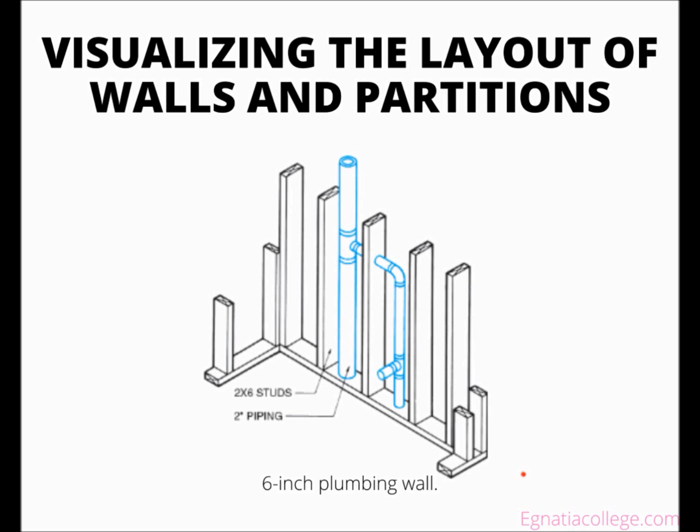Many of the dimensions of the lake house framing are referenced to the columns of the structural steel core. The faces of some of the walls are 1 inch or 2 from the center lines of the columns, but for the sake of visualizing the layout of the house, these centerline dimensions are close enough to develop a good mental picture of the layout. The north-south dimension of the playroom is 28 feet 3 inches. The east-west dimension of the north part of the playroom is 14 feet 1 inch. The section of the playroom with the fireplace is 13 feet 10 inches by 13 feet 10 inches.